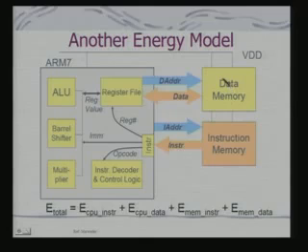For the purpose of energy modeling, when the energy model is proposed, conceptually this has been considered differently because you will be fetching instructions from the instruction part of the memory and data from the data part of the memory, and there may be characteristics of the data or of the instructions which may play a role in the energy computation. That's the reason why they have been modeled separately. In fact, the energy model that we are talking about has been built primarily through experimentation. It may involve simulation, and it can actually involve implementation with the true hardware.